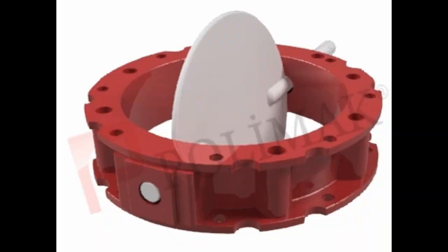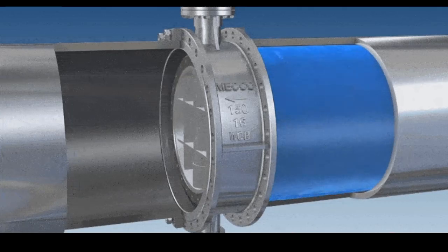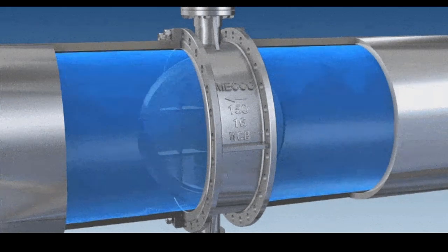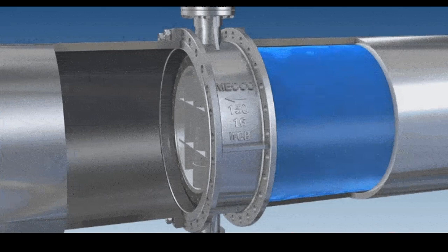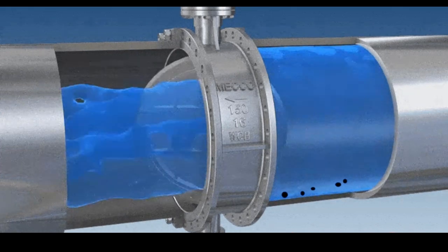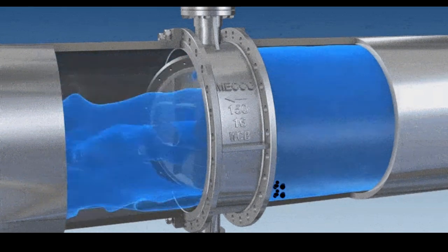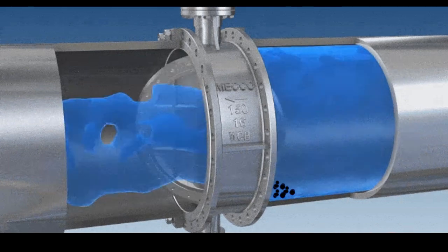For butterfly valves, the valve has a spindle across the valve bore. The common error made by the designer is to arrange the valve with the spindle vertically, where the bottom of the spindle is located at the bottom of the pipe. This orientation will easily cause the debris or particles to trap at the bottom of the spindle. After a long period of time, the debris will continue to build up and accumulate until the valve operation is blocked and could not be fully closed.